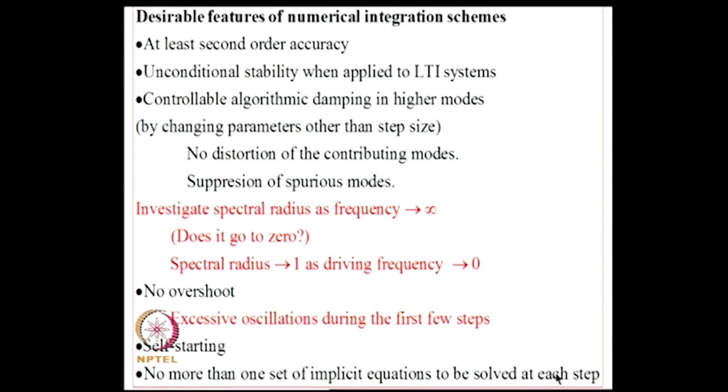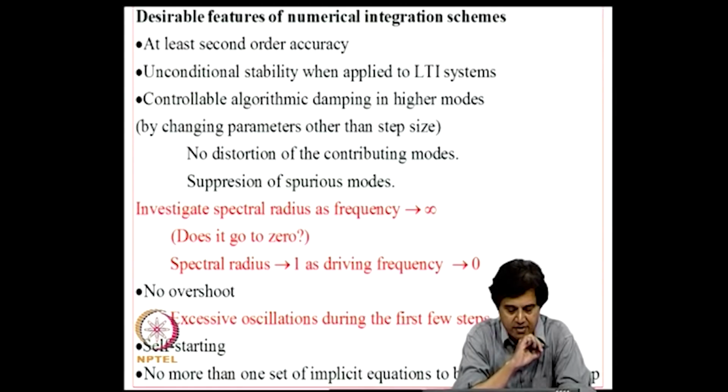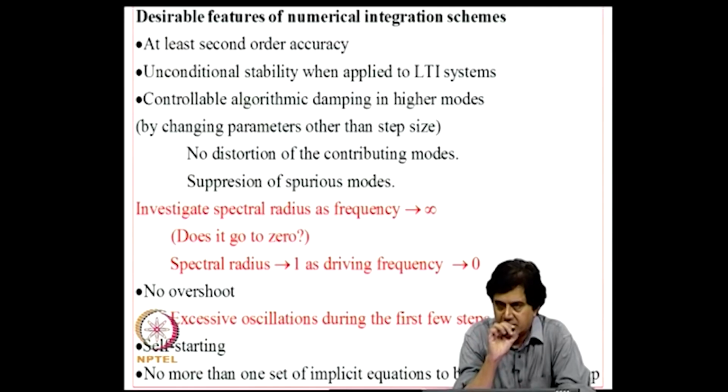So, the concerns here are, let me summarize. If you are carrying out a dynamic analysis of a structure, you make a finite element model. While selecting the size of the model, you have to keep in mind the highest frequency that is present in the excitation.